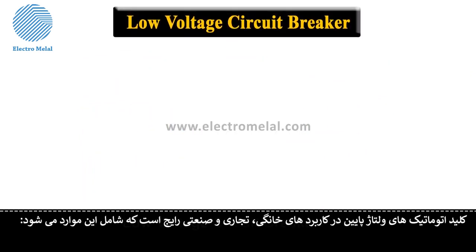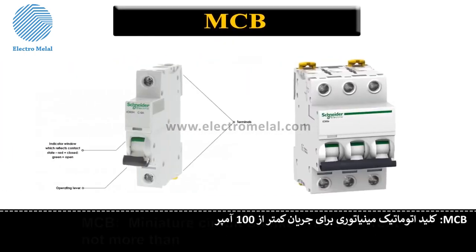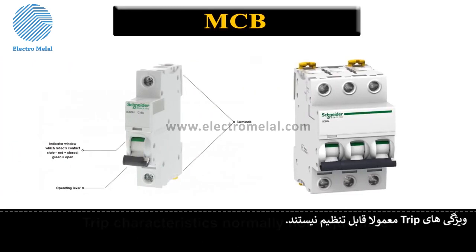Low voltage circuit breaker. Low voltage circuit breaker types are common in domestic, commercial, and industrial applications. MCB, miniature circuit breaker, rated current not more than 100 ampere. Trip characteristics normally not adjustable. Thermal or thermal magnetic operation. Breakers illustrated above are in this category.